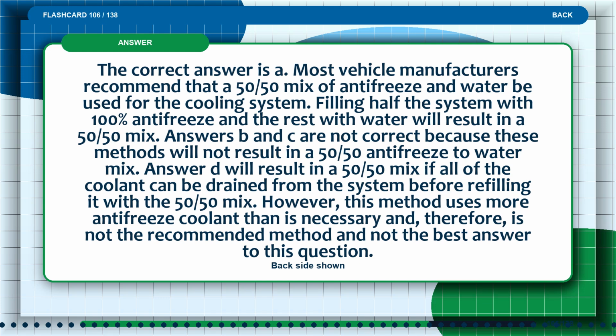The correct answer is A. Most vehicle manufacturers recommend that a 50/50 mix of antifreeze and water be used for the cooling system. Filling half the system with 100% antifreeze and the rest with water will result in a 50/50 mix. Answers B and C are not correct because these methods will not result in a 50/50 antifreeze to water mix.